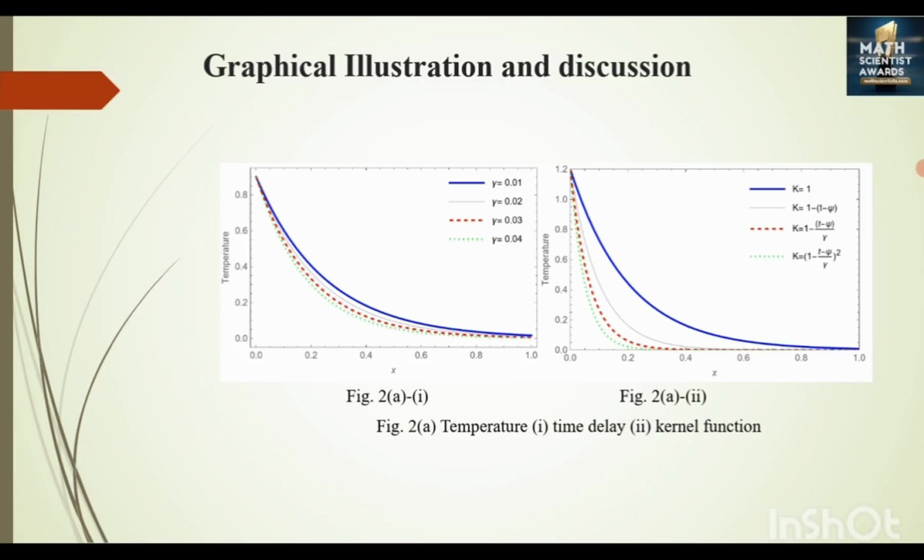For a range of time delay parameter values, figure 2a1 displays the temperature distribution along the x-axis. At first, the temperature function has a high value because of the effect of temperature-dependent thermal shock. This value further drops when the time delay parameter goes on increasing. In other words, the more time delay, the smoother the temperature distribution. This behavior aligns with the findings in references 43-44, since the thermal waves are smooth, continuous and attain a steady state based on the time delay. The particles are able to transfer heat to one another with ease, which causes the temperature to drop more quickly